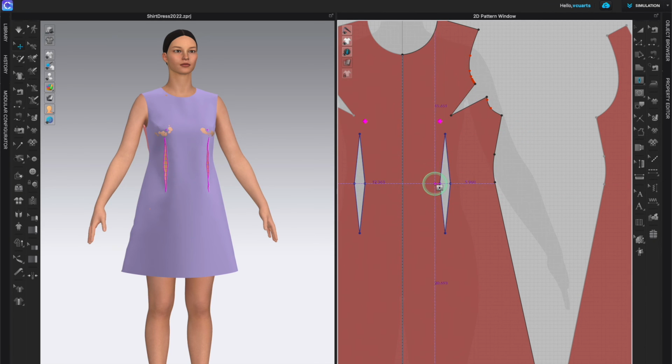But when you're pulling and dragging out a dart shape like this, it automatically equalizes everything. It makes a symmetric dart. So our top area is the same size as our bottom area, which is never the case when you're patterning a diamond dart. So expect to edit this.